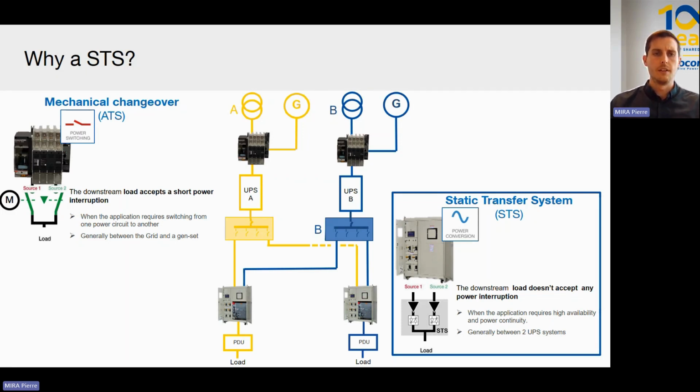An ATS, as you are seeing on the slide, is upstream of the installation. It's connected between utility and genset in order to ensure the power to all the installation. So when you are losing your utility, the ATS will transfer to the genset for the genset to provide energy